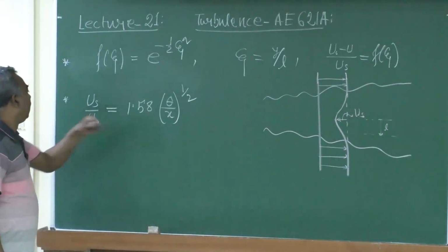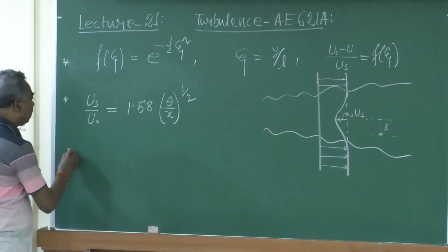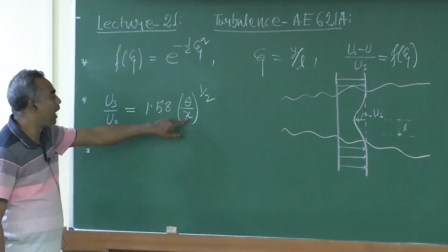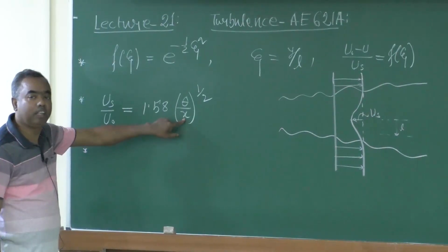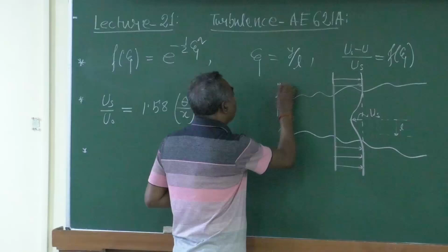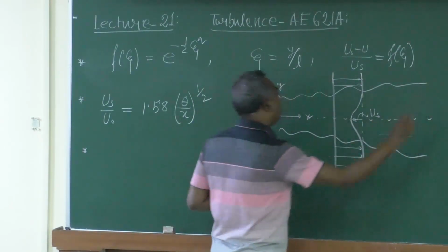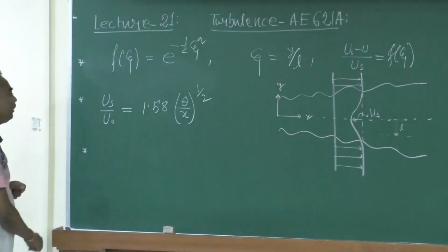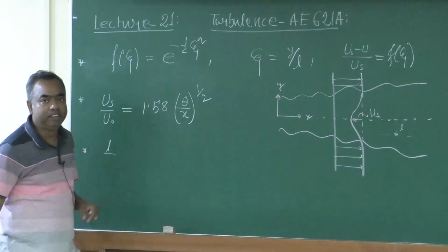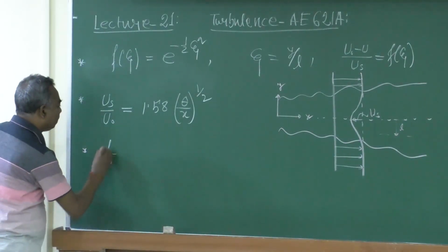So, this is our relation, and it says how us in a turbulent wake will vary with respect to downstream distance x. Downstream distance means this is your y direction and this is your x direction, and this is the central line of the wake, okay. So, we have another relation for L, the cross stream length scale, and how it varies as you go downstream, normalized by theta.